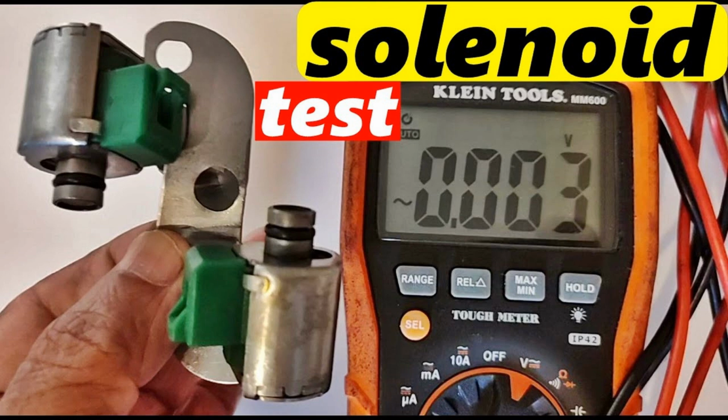By checking each of the solenoids in turn, you can easily identify the problematic element with your own hands and then replace it, if it is impossible to restore functionality by flushing. To clean the solenoid, you can use compressed air. Pressurized air is fed through the solenoid. If the element passes air, the solenoid can be reused. If not, it can only be replaced.